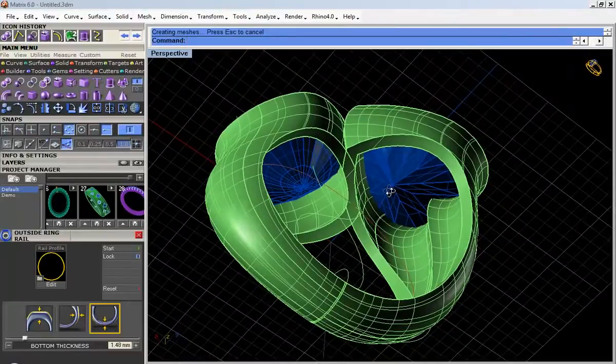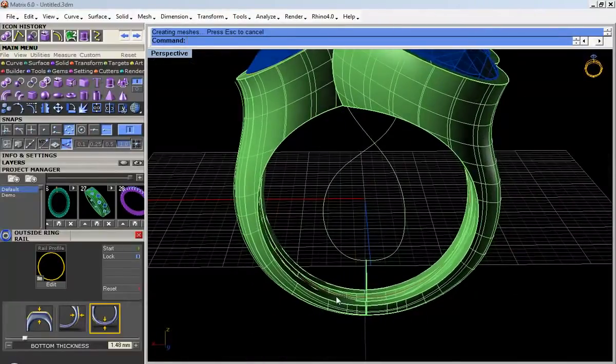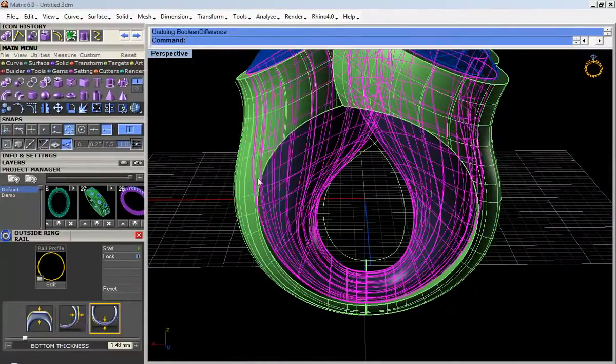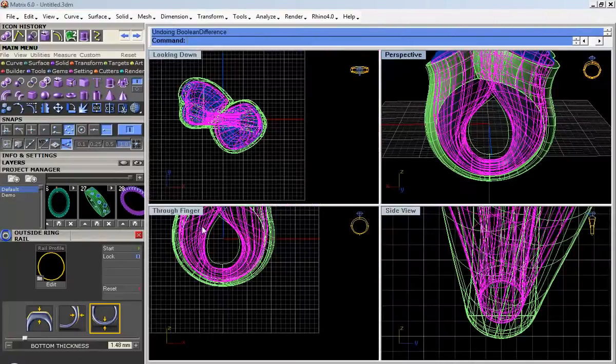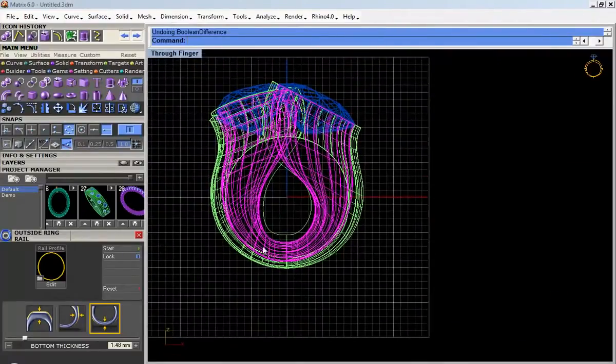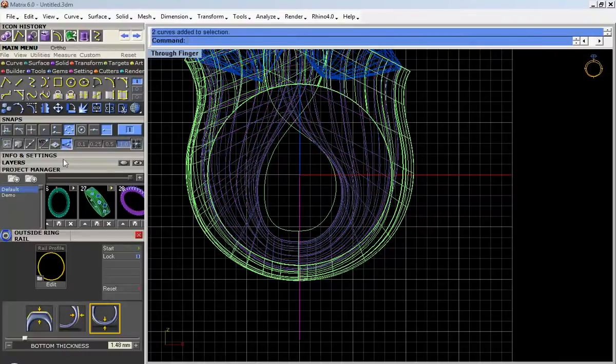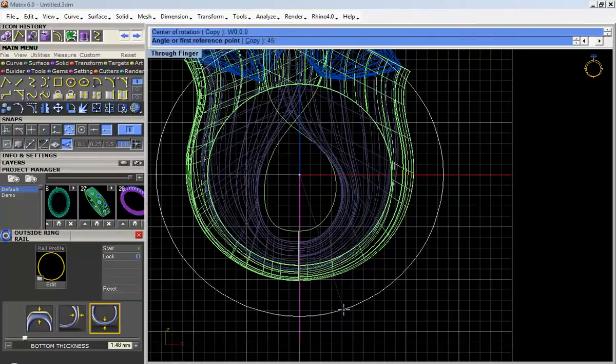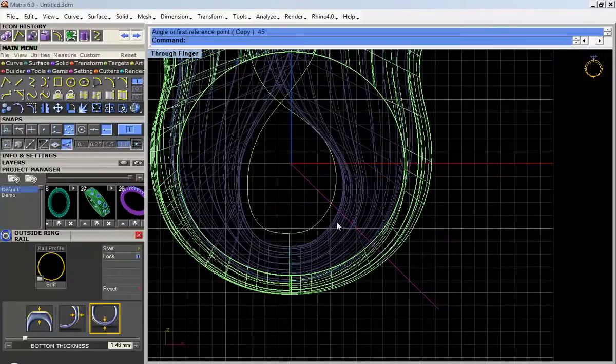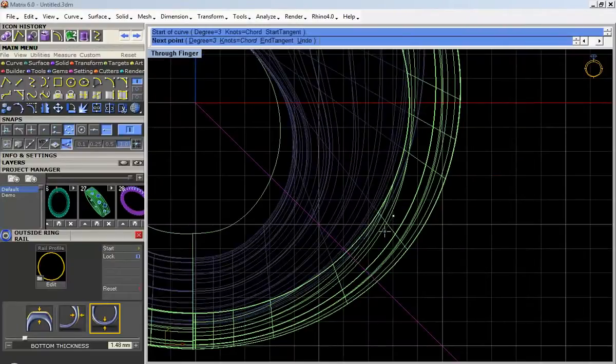But you have this part, the bottom. I know. So there's two ways you can do that. One is the cage edit we do always, or else you can have one curve straight down. Let's say you want to scoop 90 degrees, so you type rotate, center, F4, 45, enter, like this. Okay, and now I'm gonna get a nice curve coming out of here.